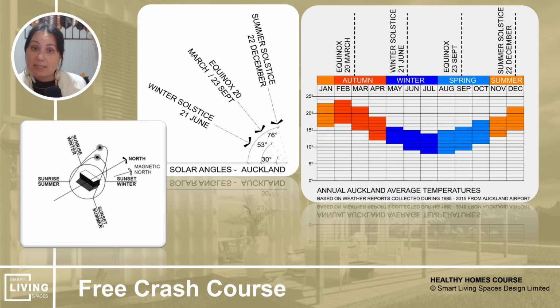Now, of course, glazing type does help. We cover this in the course, but that's a balancing act too. Spending more money on higher performing glass might help with overheating, but it also reduces solar gains, so you won't get those free gains in winter. So there is a sweet spot. To help with overheating, we also need good ventilation systems that work when we need them, not just when the wind blows and when our windows are open.